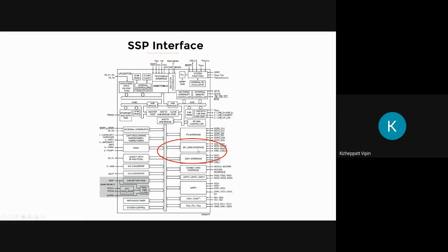The reason, as I mentioned in the previous class, is that both of them share the same interrupt line. So when you get an interrupt, you will have to check whether it is coming from SPI or SSP0, because they are sharing the same channel. That's why they are shown together, but you can use SPI and SSP0 concurrently. It's not like it is a single block. Now SSP1 is here. Both are sitting on our APB bus.